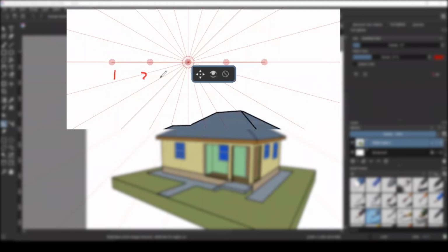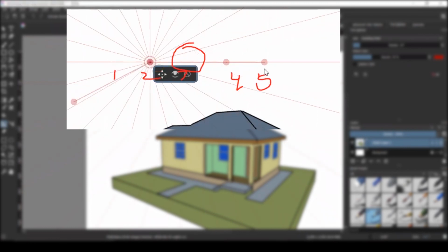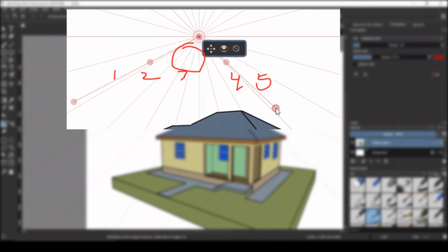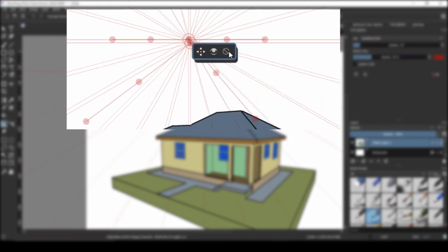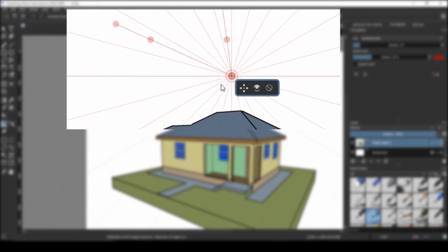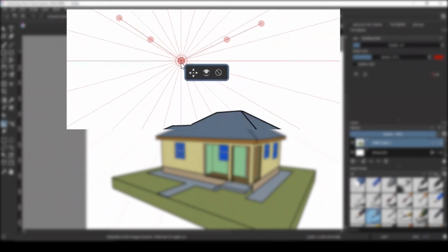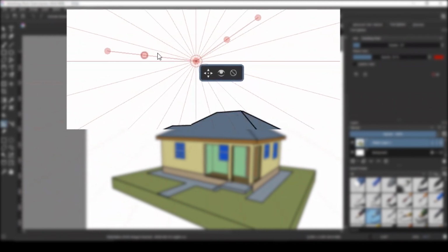And by doing that, we can just click here and it will go onto your screen once you bring it in. It comes in default like that, and it has 5 options. The reason why I said 4 options is because I never interfere with the midpoint, which is the actual vanishing point. I always adjust the outer levers first, and then I set up the inner points. Then readjust the outer ones, and that's how I get my vanishing point there.